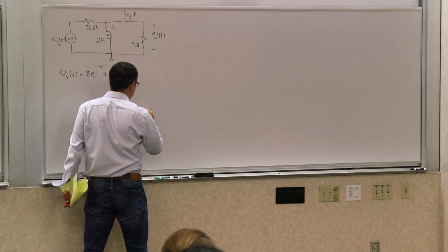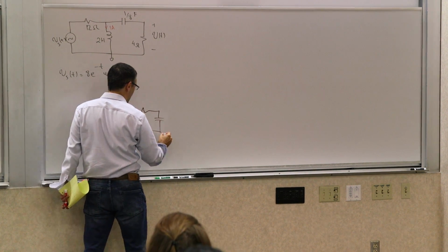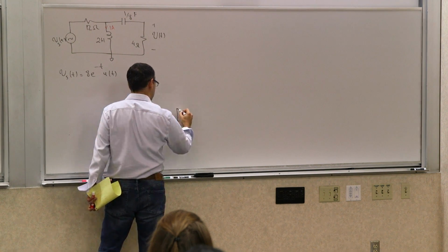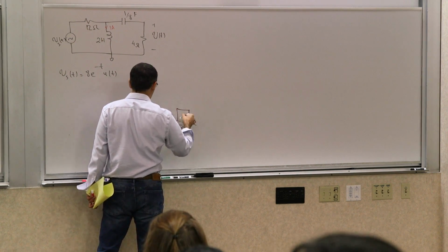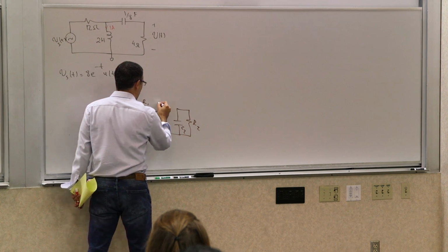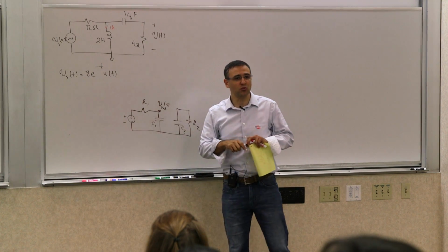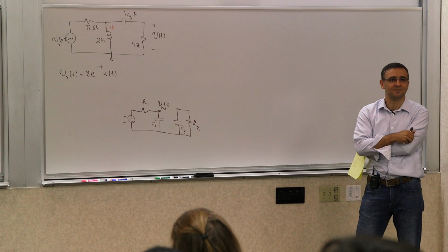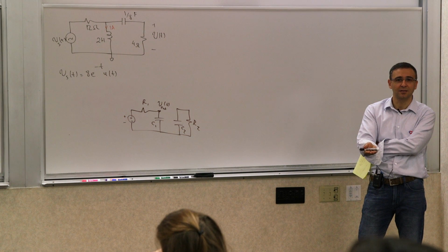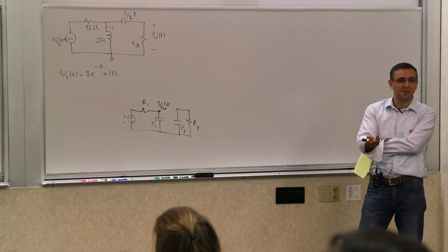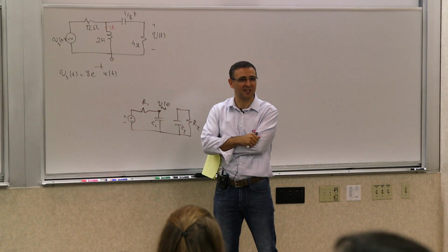So let's say I show you a system like this. So this is C1, C2, R, whatever, R1, R2. And I say this is my output. And if I use the rule I gave you, what is the order of the system? How many degrees, how many initial conditions can I define? 2, right? But if you write a transfer function, do you agree from here to there it would be a first order system? Yes, right?